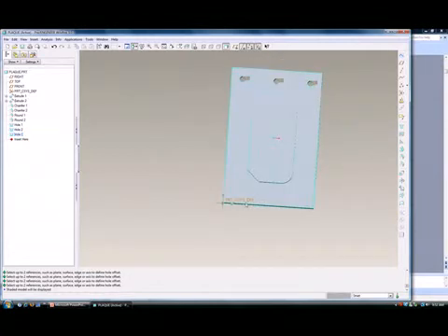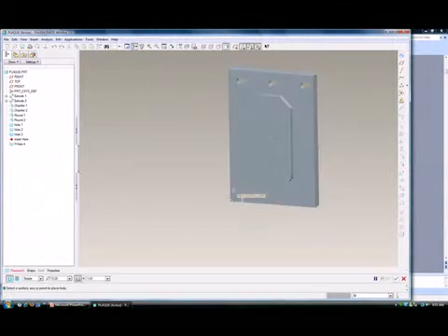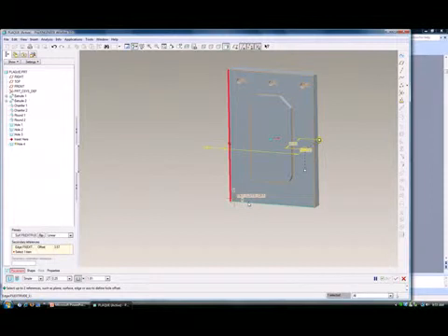So we still need to add 2 holes on the bottom. So what we'll do is we'll go back to home. Same thing. Select the surface that we want to put a hole on. Oops, I put it all the way up here. Usually if you click it here, the hole is automatically generated here. So same thing. I'll click add 2 references to this edge here and this edge here. Oops, sorry, I forgot to hold down the Control key.